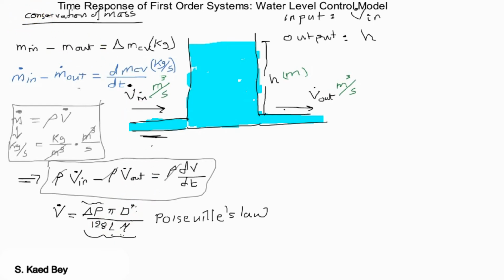Therefore, the pumping power requirement for a piping system can be reduced by a factor of 16 by simply doubling the pipe diameter. The main reason the Poiseuille law is mentioned here is just to show that the volumetric flow rate is directly related to the pressure.